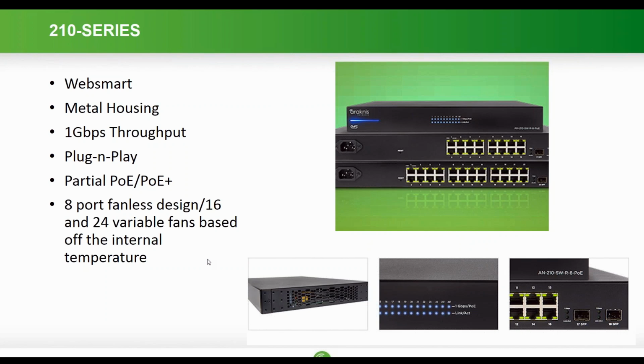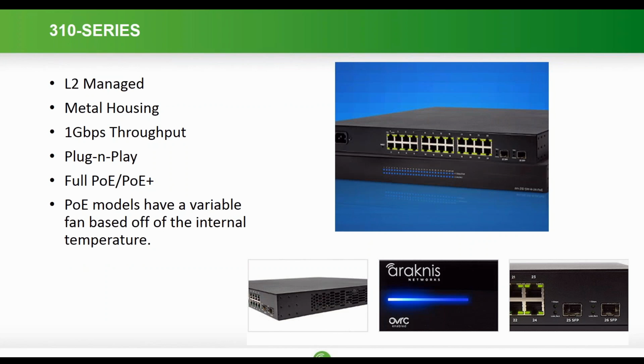But the cool thing about the 210 is that, because of a lower power budget, the 8 PoE of the 210 is fanless. We do not need a fan to dissipate the heat from that unit. So that's very interesting, because now you have an 8 PoE model that's completely silent. And then the 16 and 24 PoE have the variable speed fans we talked about. The 310 is a complete replacement of the 300, so nothing new outside aesthetics and great quality. It's layer 2 managed, it's metal housing, it has full PoE and non-PoE options.